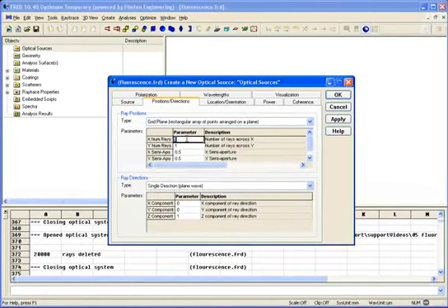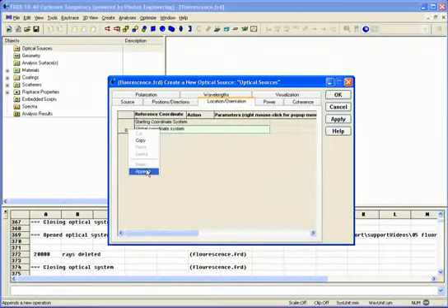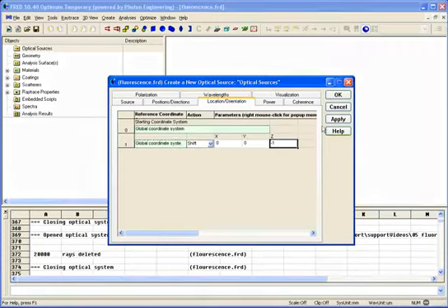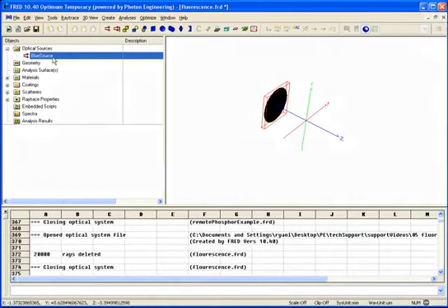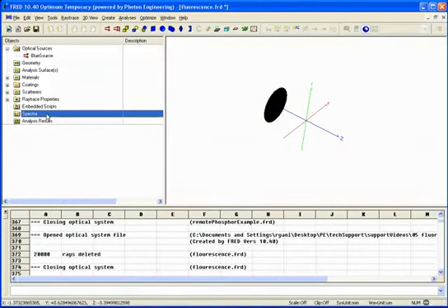Set its positions to be, let's say, 301 by 301 on the ray grid. Half a millimeter is fine. I'm going to go ahead and make it elliptical. It's going to be traveling in the positive z direction. I'm going to offset this slightly from the origin by -1 in z and hit apply. Okay. Now this particular source, I haven't assigned it wavelengths yet, so I'm going to go ahead and use FRED's